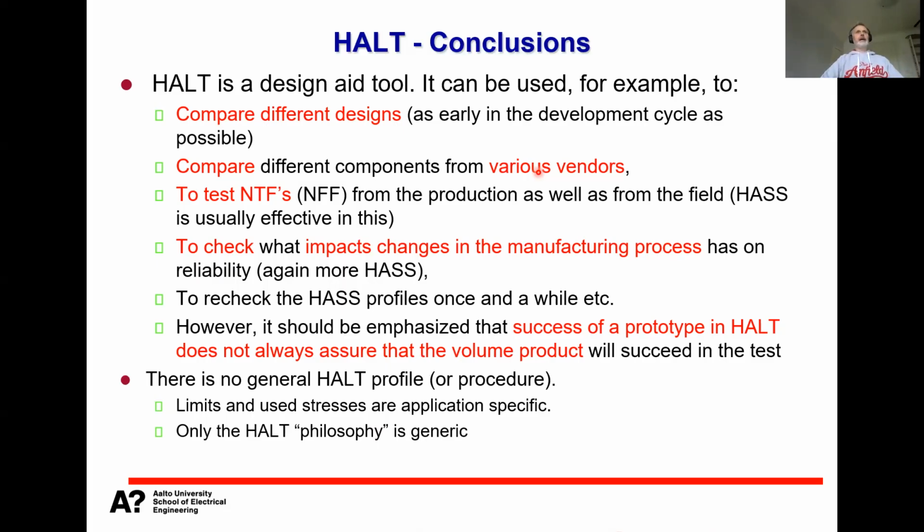And then there are NTFs or NFFs, meaning no trouble found or no failure found. For a field return where you can define what is wrong, you can use HALT testing to bring up the problem. You can check the effect of changes: if you change something, take a new manufacturing process, a new component, a new material, then you can see how that affects things.